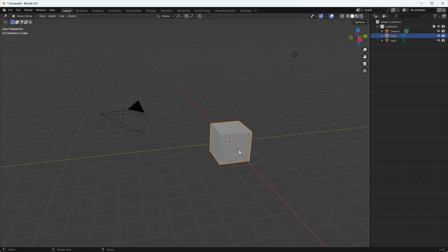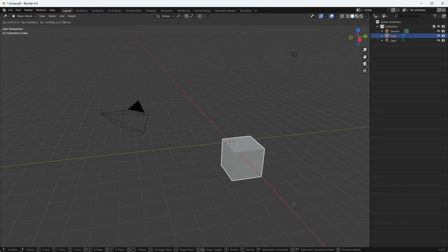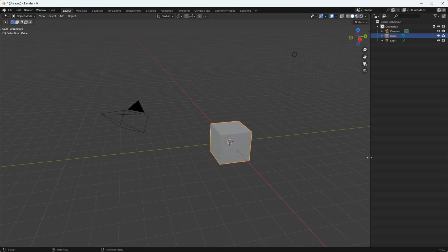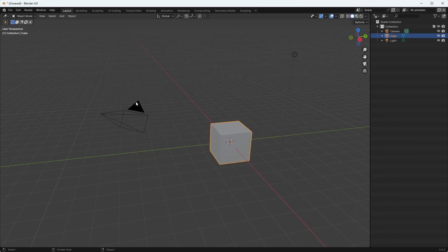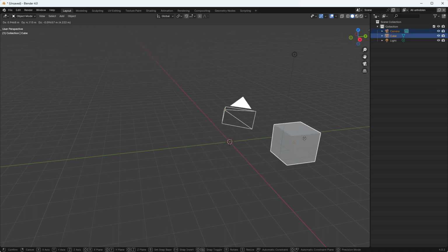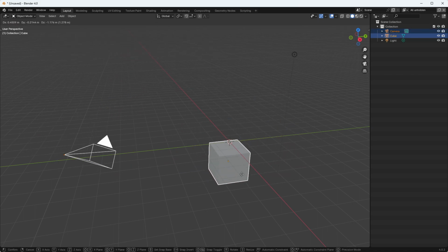And then we get into just basic transforms. We'll touch a lot more on these in the shortcuts video, and the modeling video probably. G is for grab, and G enters a modal. Remember in the last video we right-clicked and then got the split to get a modal that we can left-click to confirm, right-click to cancel. Same thing here. G lets us grab and move whatever object or objects are selected. G, and then right-click to cancel or left-click to confirm.